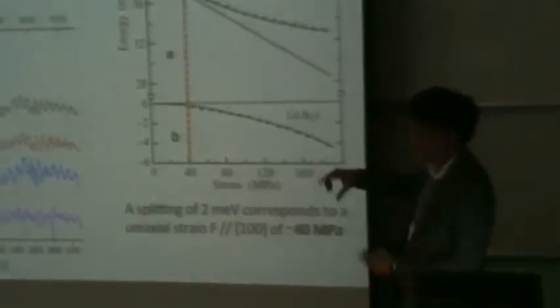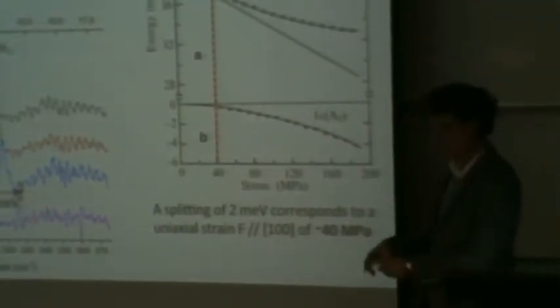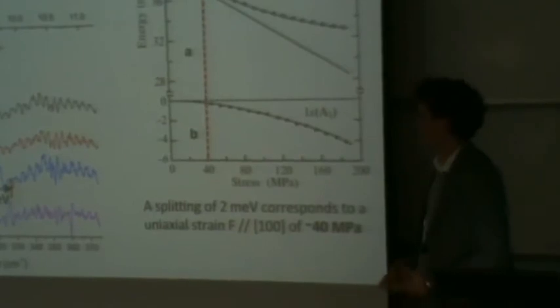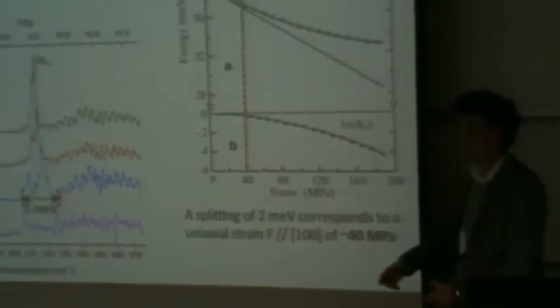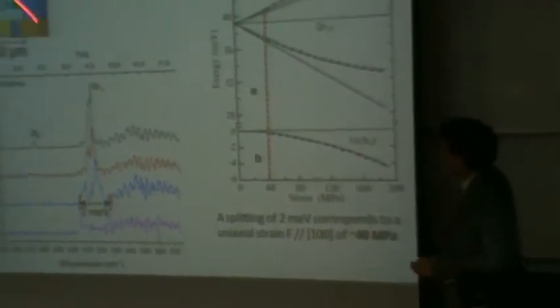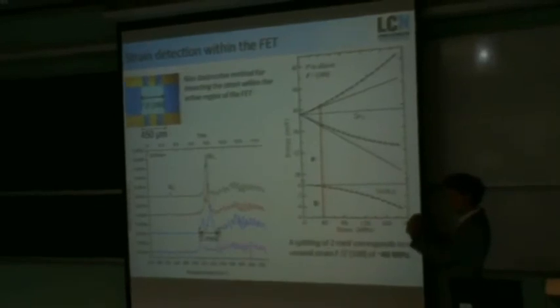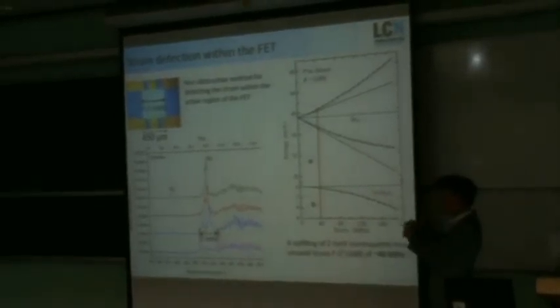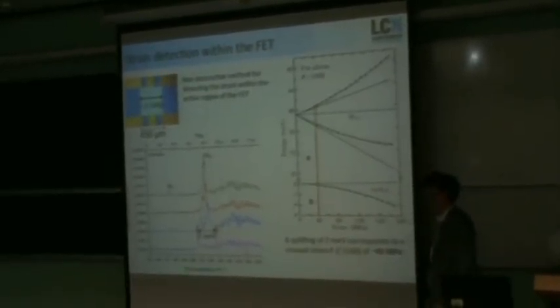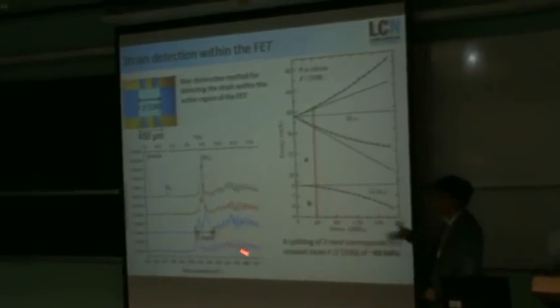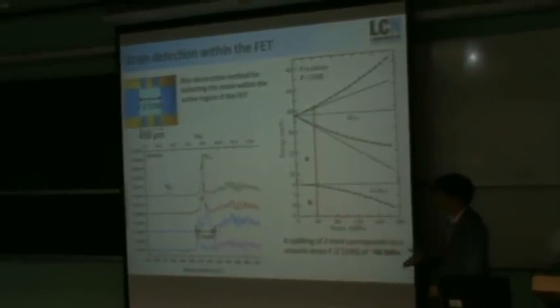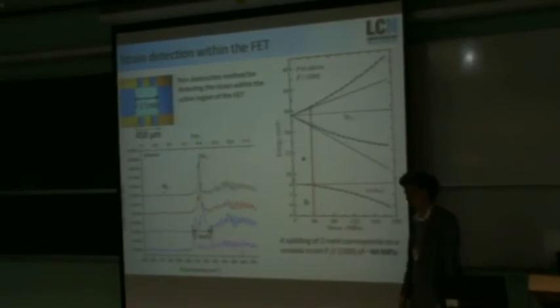These device sizes are 8 millimeters square, so it's not a small wafer that it's mounted on. What's interesting though is that because it's silicon on insulator, I think the strain is quite easily transferred to just that top region. And I think that's actually quite important. Basically this strain is locked in. The device is strained permanently.